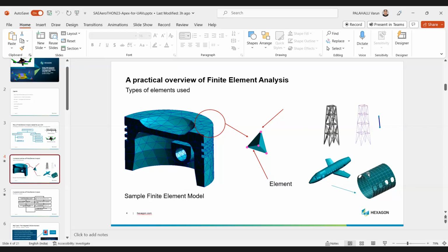So you can take a look at what is a Timoshenko element, what is a Timoshenko plate, and then what is a Mindlin element. So these are all finite element approaches. And these are approaches that are made for bodies which do not have a thickness which is very high in the Z direction. That is, it only has planar dimension, but the Z axis is very thin.